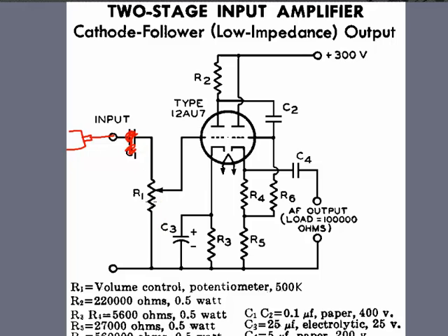So as you turn this knob the other way and you put very little resistance down on this end, and based on the resistance on the top side of this thing plus some of the other resistance on the other side of this circuit, we'll talk about more later, you've given a really easy path to ground, which means very little of your current's actually going to make it into this amplifier. In other words, the amount of voltage being applied at this point because of this voltage divider rule here. Remember, we're kind of playing with whatever voltage is here, and we're kind of sliding it up and down as we turn this potentiometer, but you end up with less voltage right here on the input of this tube. And since tubes are voltage amplifying devices, if you have less voltage here, you will get less voltage out over here, which ultimately reduces your volume going to your speakers on this side.